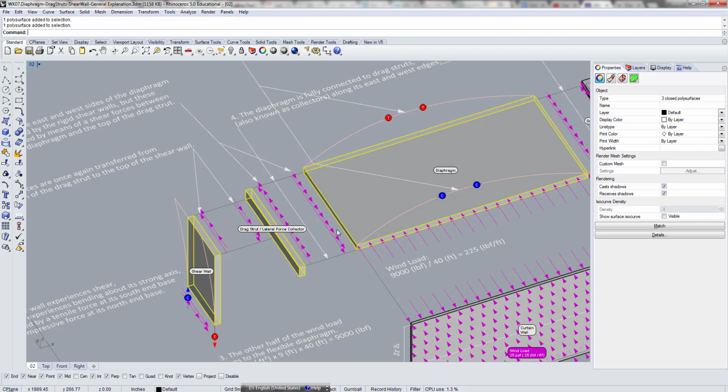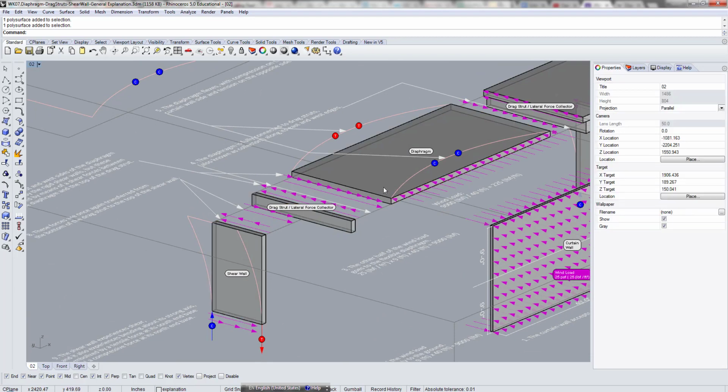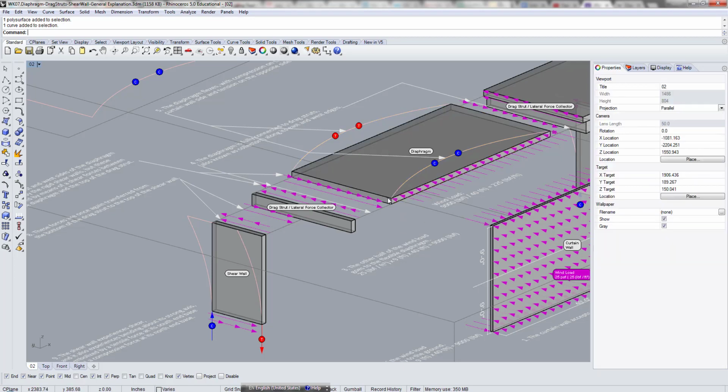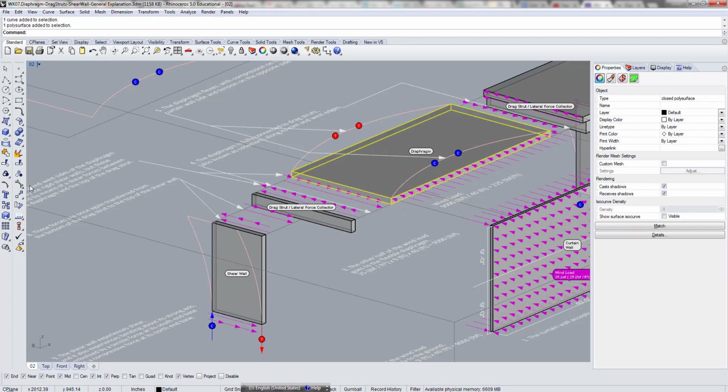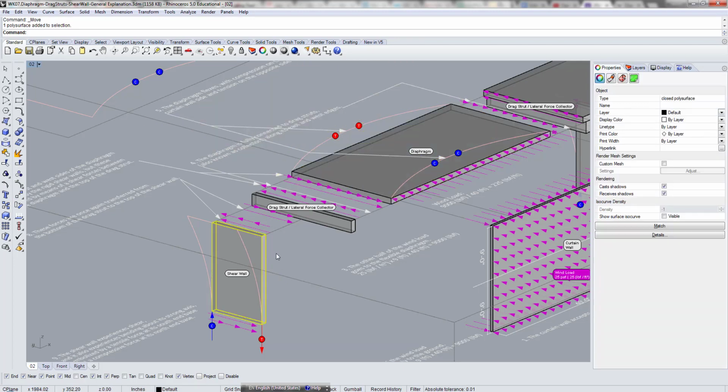If you observe these three elements, this one is trying to flex, right? It's actually flexing, and at the edge it's wanting to move, so it's trying to move this way. The wall is trying to resist that.